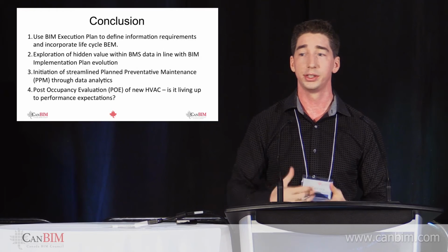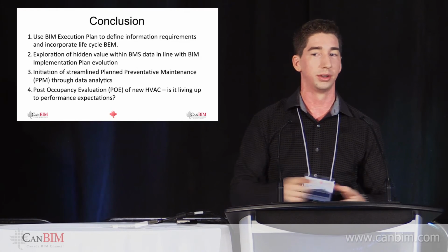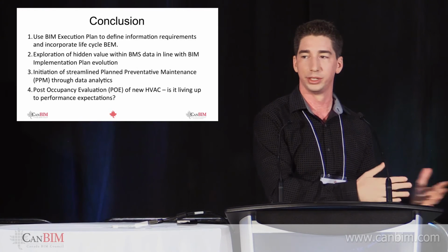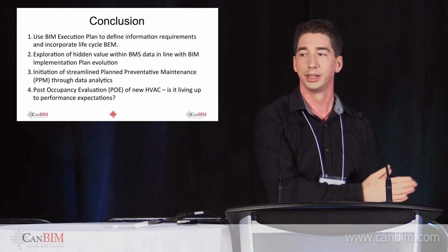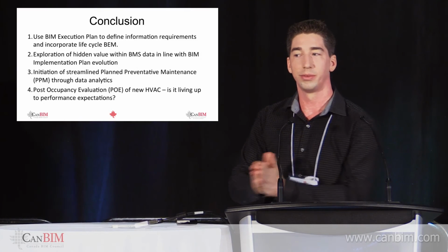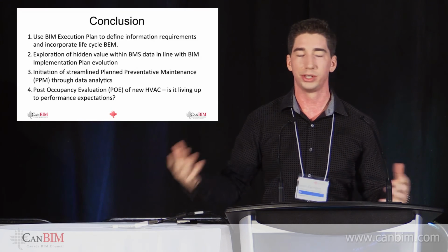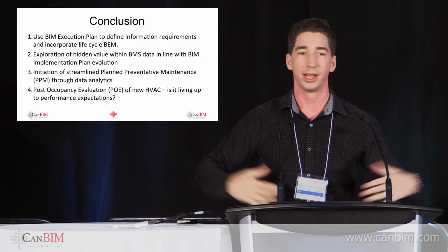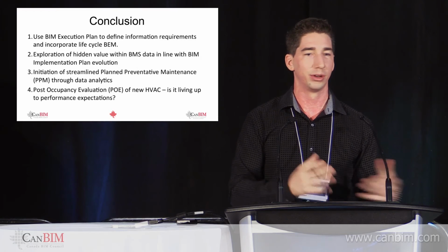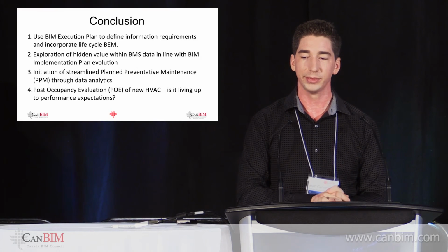If you want to do natural ventilation, great, I support you, but we need to know about your windows and your crack openings. We need to know what's happening at the beginning, and then verify all the way through to make sure you're performing the way you should. Because when you change your window-wall ratio, everything changes. When your load changes, your systems change.